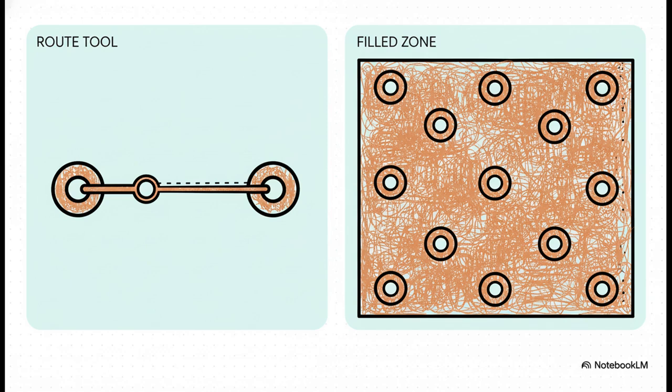All right, it's time to connect the dots. You basically got two main ways to do this. First, there's routing. You hit the X key and you literally draw the little copper highways that the electricity will flow through. Now, if you hit a roadblock on one layer, you can just press V to drop in a via, which is like a tiny elevator that takes your connection to the other side of the board so you can keep going. The other method is to add a ground fill, which is like pouring a giant sheet of copper over your entire board. This is awesome because it automatically connects all your ground points and makes your whole circuit more stable. It's a massive time saver.